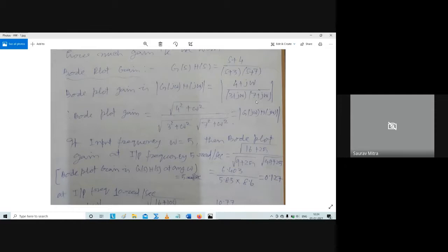So this is the difference between root locus and Bode plot. In root locus, we had been changing the value of K from 0 to infinity, and K was a gain which was not determined by frequency. But in case of Bode plot, we are actually changing the input frequency. Generally, input frequency in our lab experiments is given from a function generator or signal generator. So the same system we are connecting, and we are just changing the frequency knob.